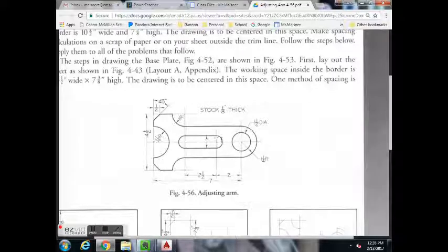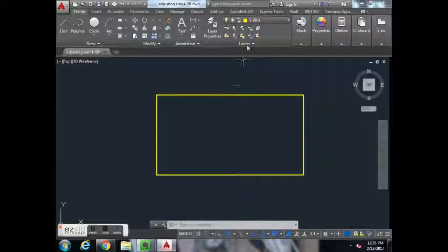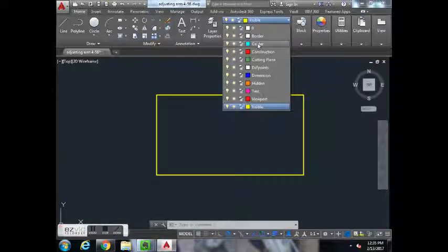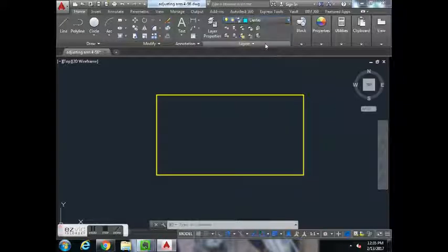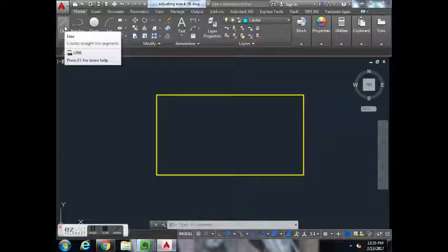The one right down through the middle horizontal is probably the most recognizable and easiest one to put in, so we'll put that one in first. So if we come up to the visible layer type, we go down to center, select center, draw a line.